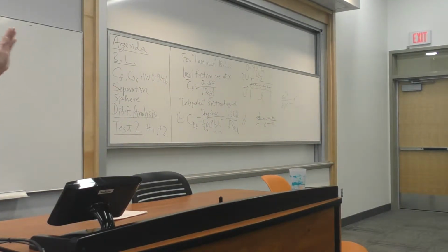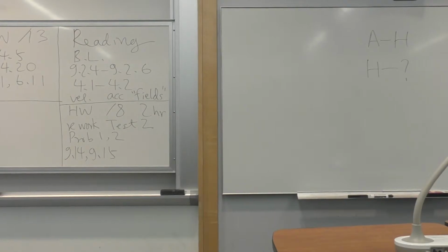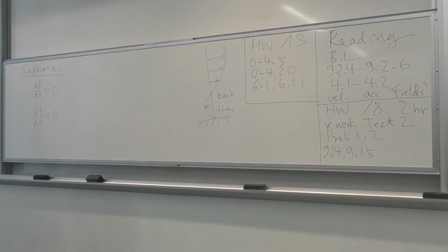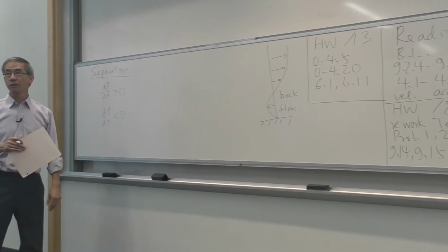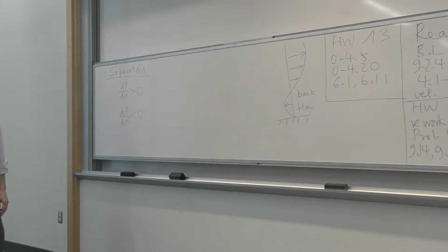So as I march downstream, the pressure is always constant, call it 14.7. No change. However, for most entry devices, and also a diffuser, a compressor, and a turbine, that's far from being the case. They have, on average, between the downstream station and the upstream station, significant pressure gradient.